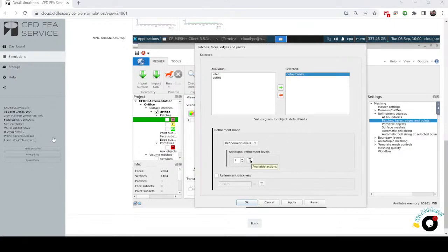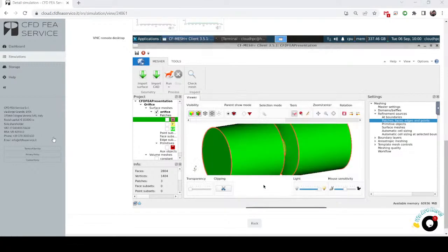And you can also here say show cell size, so it will immediately show you the cell size which you apply in this case. This can be quite useful when you're setting up a big problem, so you can visualize the cell size you're applying. In that case, it takes much less time to get to the setup that will generate a nice high quality mesh.